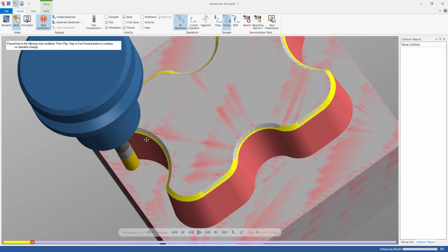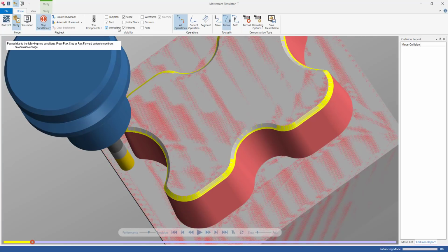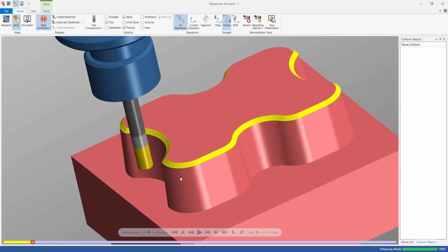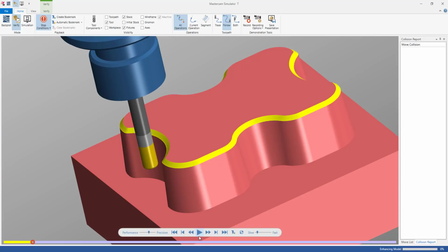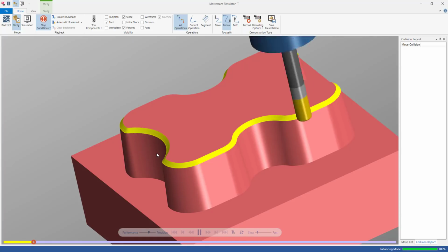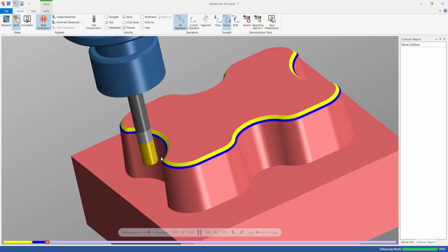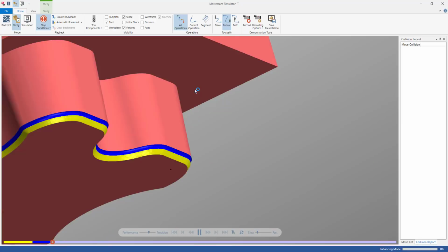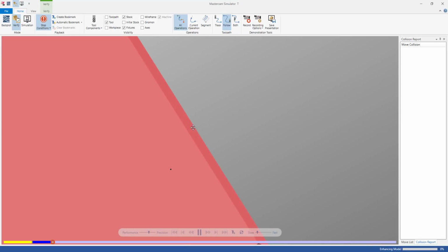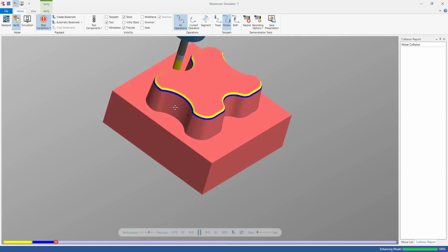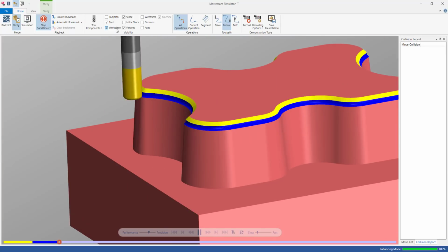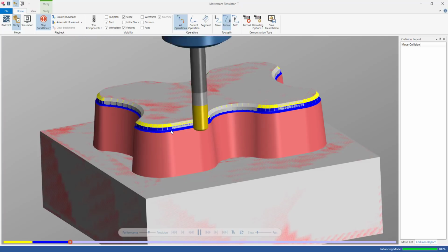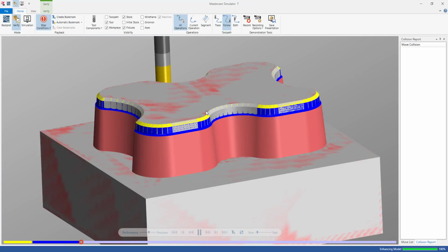And we keep going with the second toolpath. Oh, my computer is slow. Okay, and turn on the workpiece, and you can see the tool will follow the workpiece. It does not cut into the material. So we have a correct toolpath.